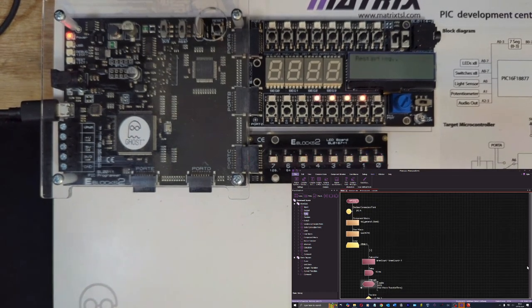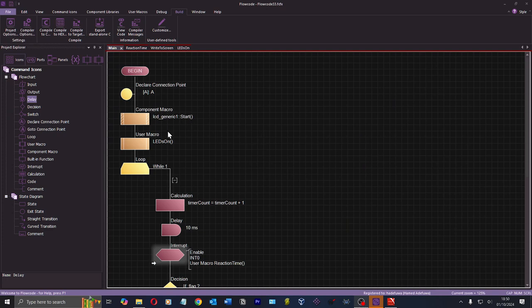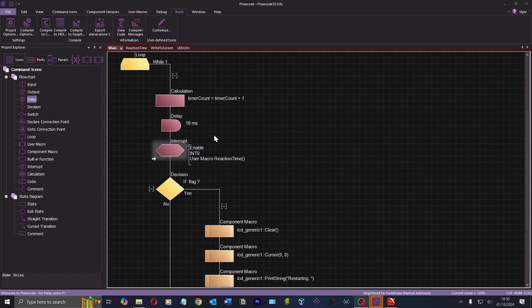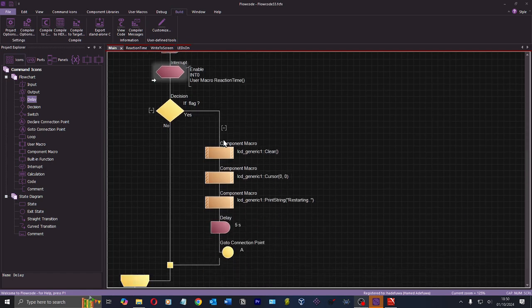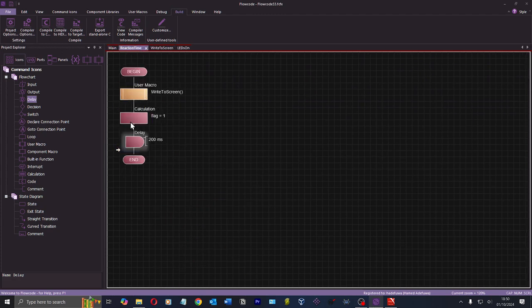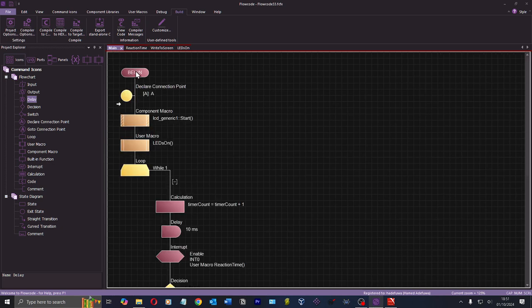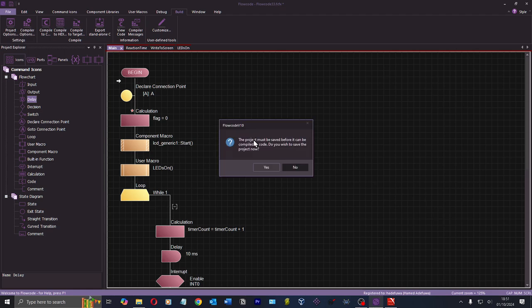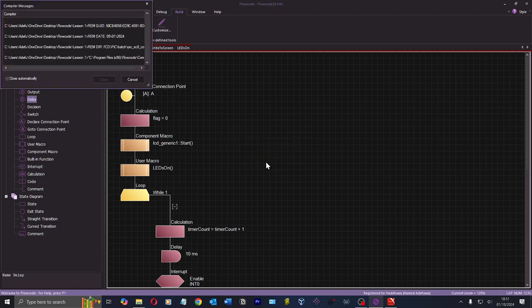So what's happened there? We turn on the LEDs. Then when that's done, we go into here and start incrementing the timer counter every 10 milliseconds. We're checking if the flag is set. So I guess my flag is 0? We don't know. So let's set my flag to 0 in the beginning of my program. My flag could be whatever, right? Undefined at that point.